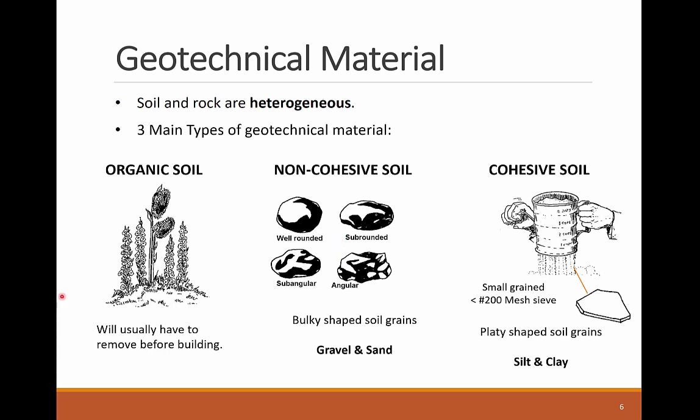sand in itself is not a stable material to form the walls of the sandcastle, as it tends to be stable at only small slopes of around 30 to 45 degrees. However, adding a little water generates some cohesion between the sand grains, which can help in making the sand stable at higher slope angles. However, once the sand dries, the steep slope becomes weaker and subject to failure.